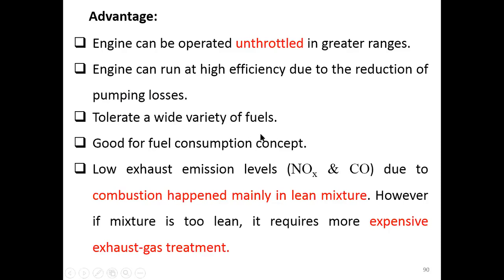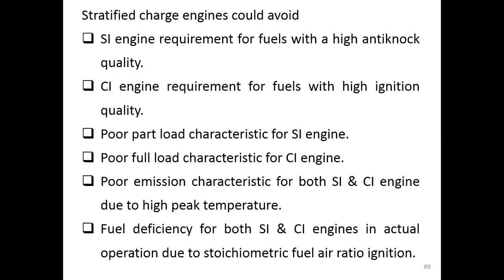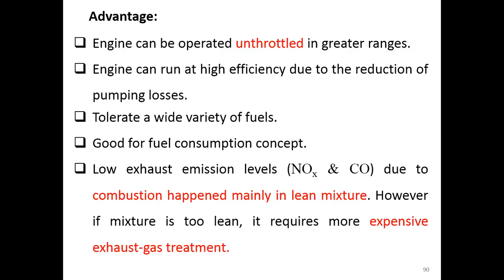They don't need to have a high self-ignition temperature or a high ignition quality, so it can use a wide variety of fuels. It's good for fuel consumption. They need not go for the stoichiometric ratio all the time. They can go for a rich mixture a little bit and a lean mixture most of the time. So it is good for fuel consumption.